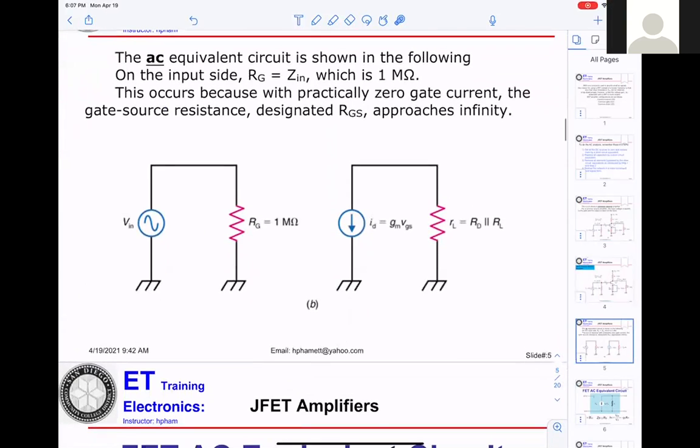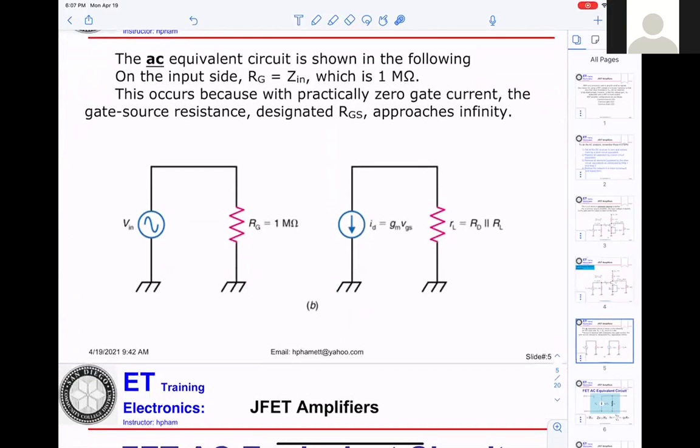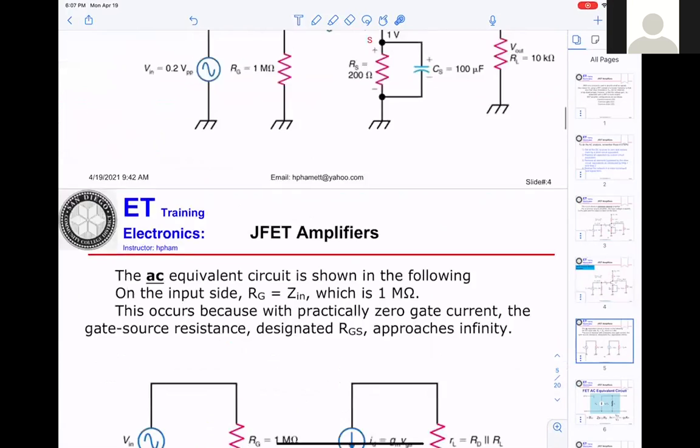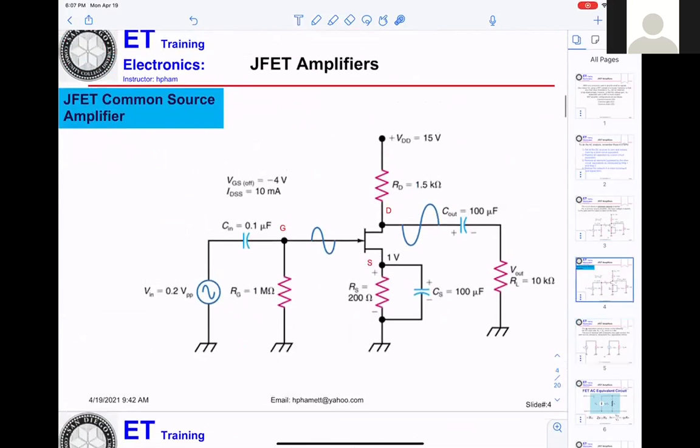Now you're right, the resistor establishes the DC operating point. But like I'm saying, if the frequency of the source was, say, 10 hertz, and you had a 0.1 microfarad capacitor, the impedance of that capacitor would be 159 kiloohms, so it would not be a short circuit. So you have to have the source frequency high enough so that the capacitor looks like a short circuit. That's all I'm saying.